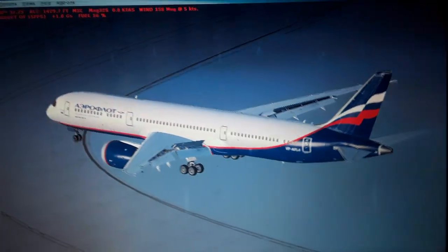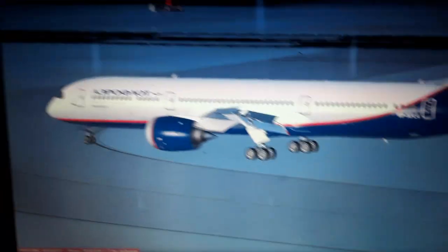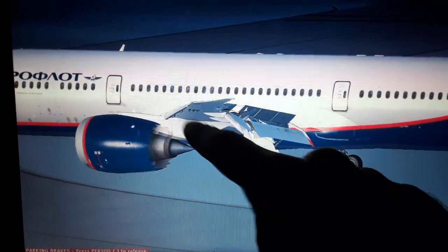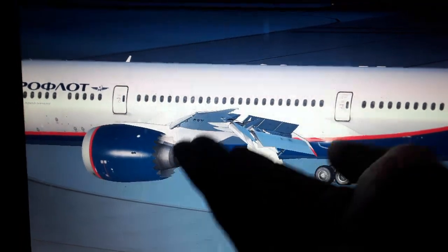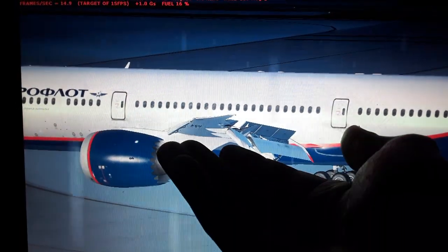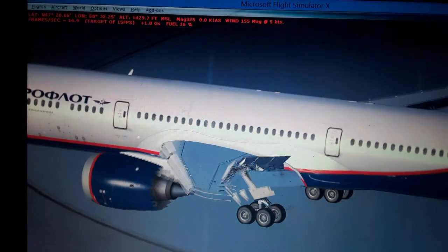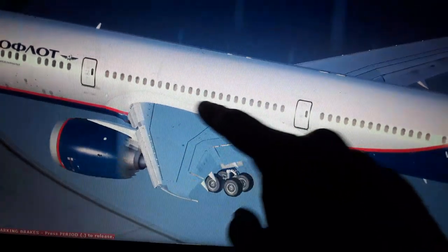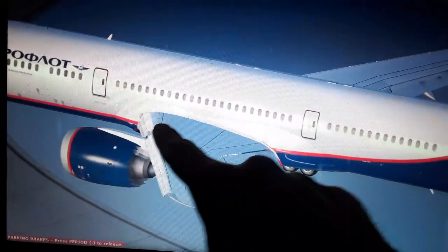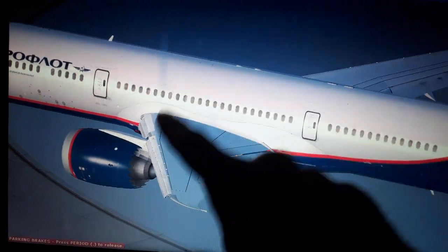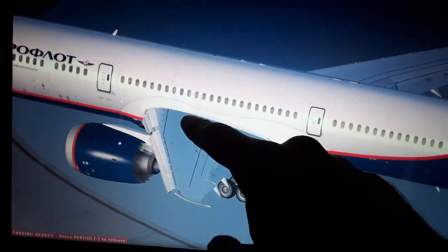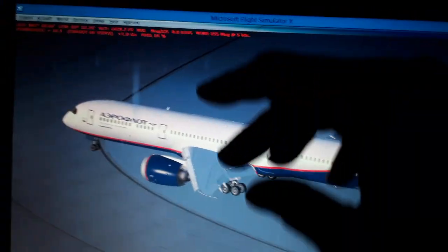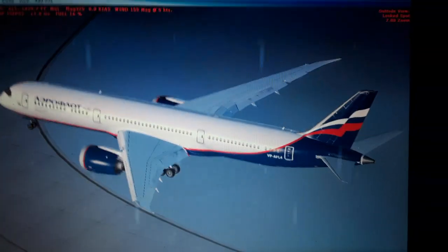So you can see the bottom surface of the wings is more flat over here. So the airflow of the air mass as the aircraft accelerates using the engine thrust is moving slower below the wings, so we have higher pressure below the wings because the air is moving slower below the wings. And as the aircraft also accelerates for takeoff, you can see the top surface of the wings is more curved, it has higher curvature, so the airflow is moving much faster above the wings. So there is a lower air pressure above the wings, which sucks the aircraft up into the air. So this is the general explanation.